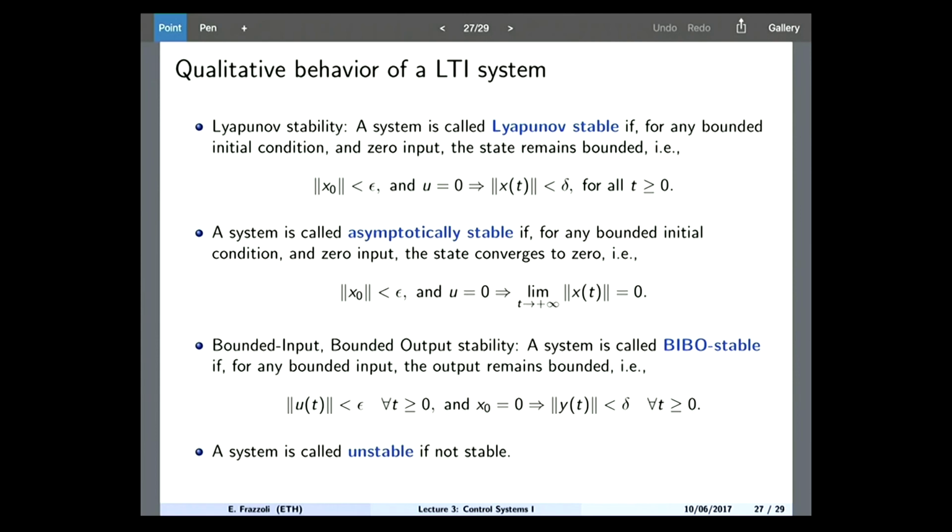Whatever the initial conditions, their effect will be forgotten and the system goes back to the equilibrium point. It is important because it allows us to essentially ignore initial conditions when studying the response of control systems. As long as we are still in the linear regime, those will be forgotten, and the system will converge back to the equilibrium point.